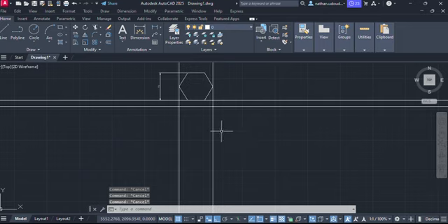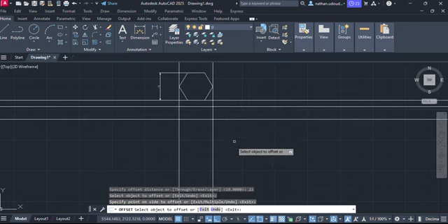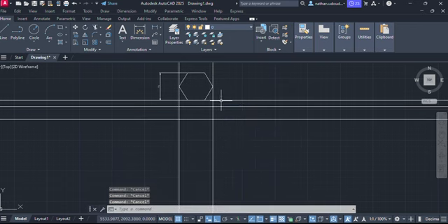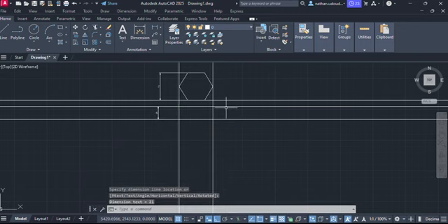So now, what is the front elevation here? The distance here is 21. So how did you get 21? You only need to take that same 30, M30, you multiply by 0.7, and that's why you have this distance as 21. So dimension from here to here is 21.